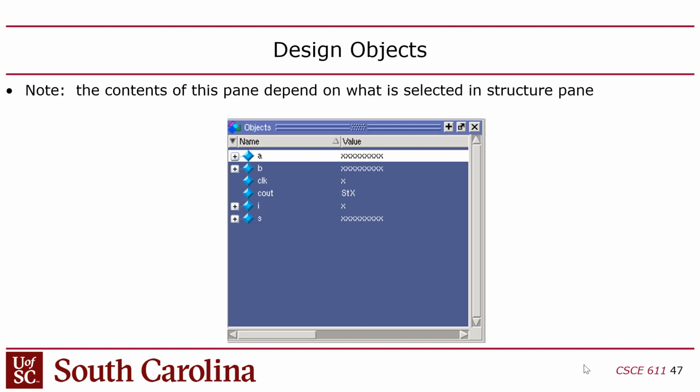carry out. Yeah, I don't actually even understand this. It has X's here, right? So that's one of the states. But then they have strong X. Yeah, I don't know why it's strong X. I can't explain that. I don't know where it gets the strong X from. I get the strong 1. That's like if you force a signal inside the simulation environment, because that strong 1 can't be overridden if you set it with a Tcl command force. Tcl is the command line language used in ModelSim. But strong X, I can't explain that.